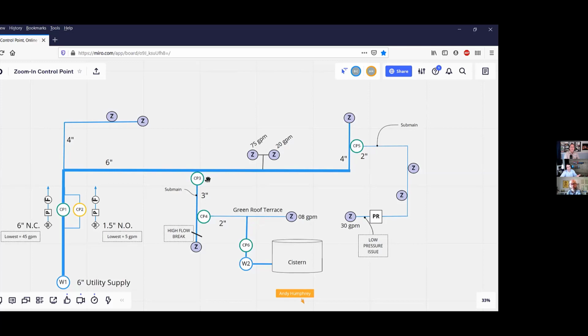And then again, isolate just that section of the pipe and not turn the entire system off at the, quote unquote, master valve, but turn it off at the control point. Right. And the big reason that designers size pipe is to save cost. It's not really a pressure thing. They don't need 6-inch pipe all the way through. But this allows them to still have their cake and eat it too, to get both.